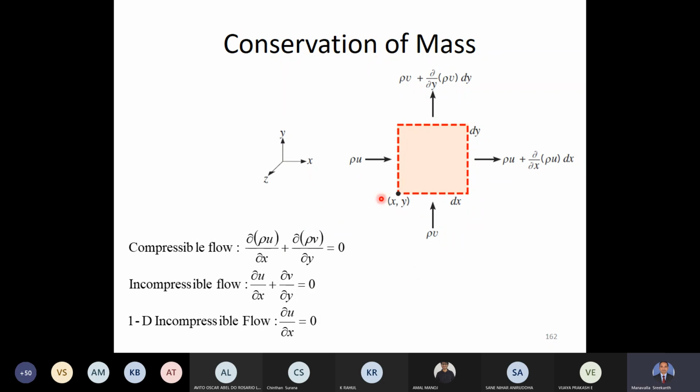Okay, so here we are talking about two-dimensional flow. The same conservation of mass is nothing but the continuity equation. So what you're seeing here is the continuity equation in 2 dimensions. And in 1 dimension, what happens? This term will vanish, and if it is incompressible flow, density will also be a constant and will come out of the brackets, and what simply remains is dou u by dou x is equal to 0. This equation is the differential form of the continuity equation A1 V1 is equal to A2 V2. That's the continuity equation that you are familiar with in fluid mechanics. This equation that you see is its differential form.